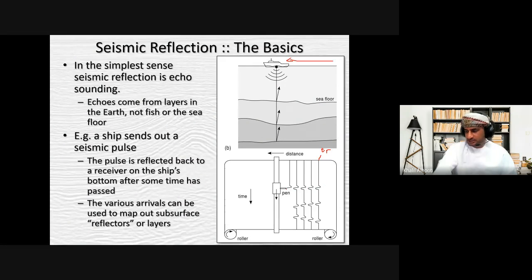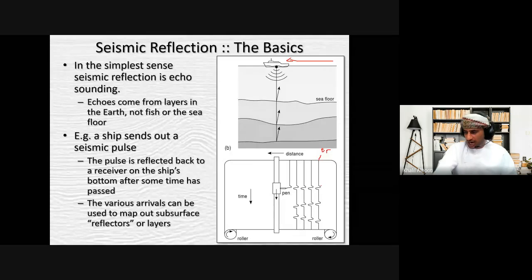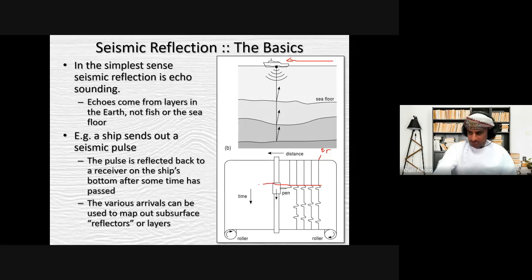The first pulses or ray of pulses from each subsequent trace tells you how deep in time the seabed is. How deep from the sea surface is the seabed, but in time. Then the second reflection, then finally the third reflection. And that's what we call echo sounding.